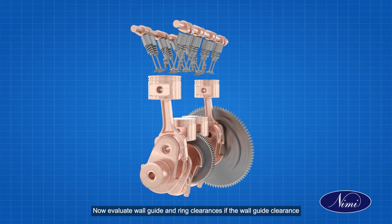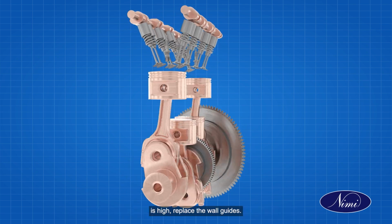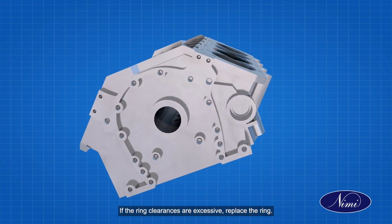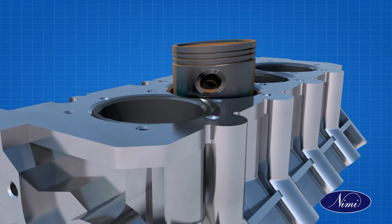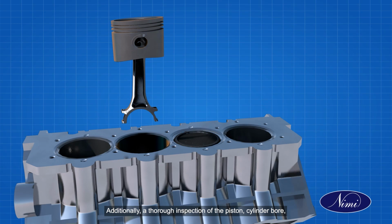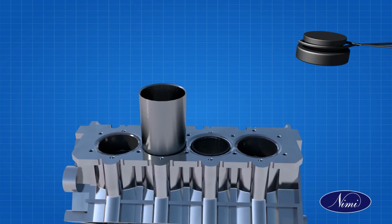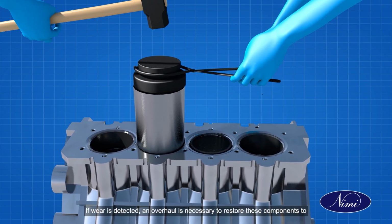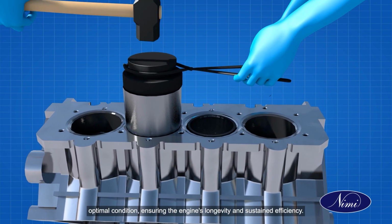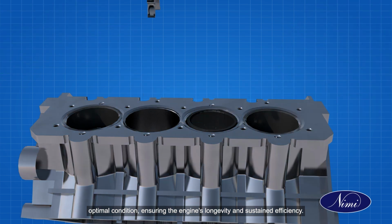Now, evaluate valve guide and ring clearances. If the valve guide clearance is high, replace the valve guides. If the ring clearances are excessive, replace the ring. Additionally, a thorough inspection of the piston, cylinder bore, or liner for wear is crucial. If wear is detected, an overhaul is necessary to restore these components to optimal condition, ensuring the engine's longevity and sustained efficiency.